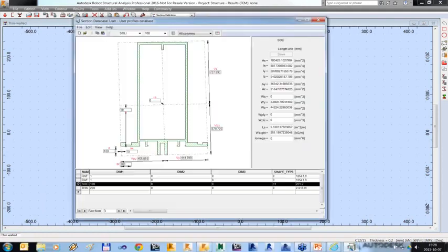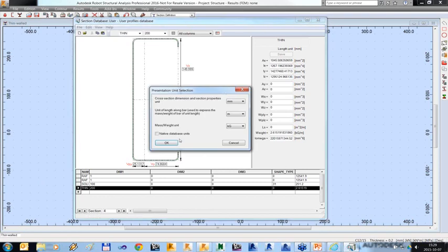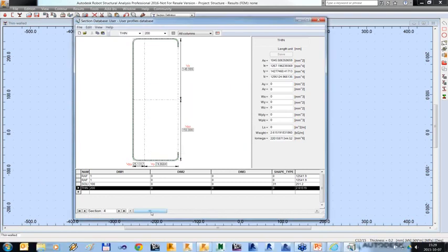And as you may see here, I have my solid section and the thin-wall section. To make any modification to the database, it's recommended to display all columns here and set the correct units we want to see. Units display is available from the view menu, then units display here. When we scroll to the far right end, we can see the checkboxes here.